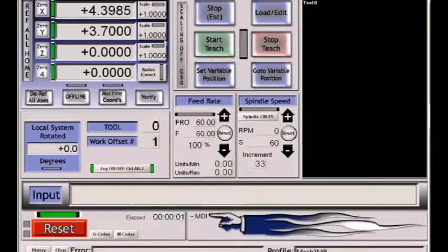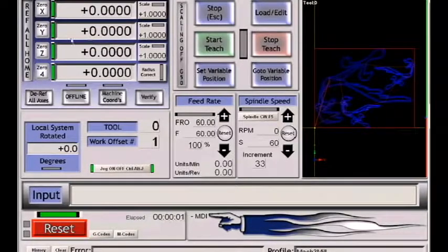If we take a look at the MDI screen, again we have our DROs repeated. It's handy to have DROs on most of the screens so you know exactly where your table is at. We have 0 buttons for zeroing the axes, and another reference button here, the scaling. Radius correction is used for 4-axis work, where you can tell the system the actual circumference size of the object, and it will correct the feed rate to create a tool path that feeds at the correct rate on the circumference of a rotating object. Again, something that you can ignore unless you understand what they're for.